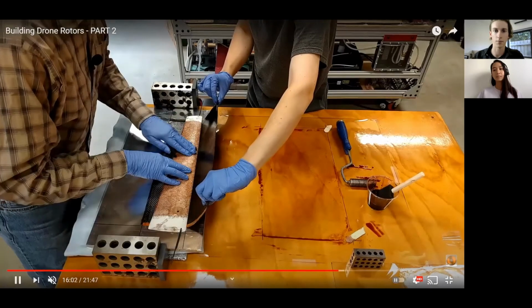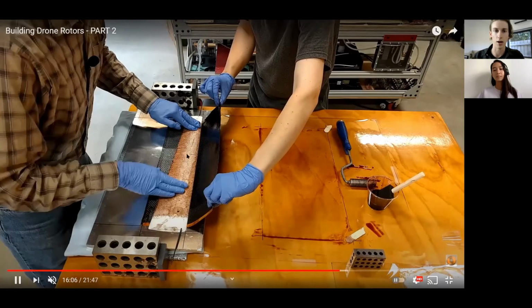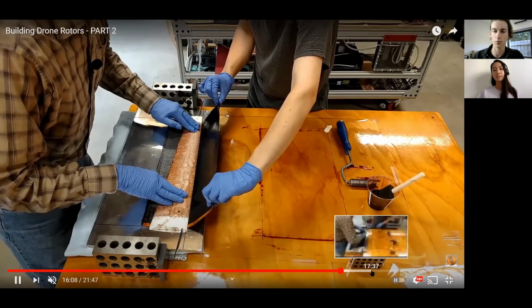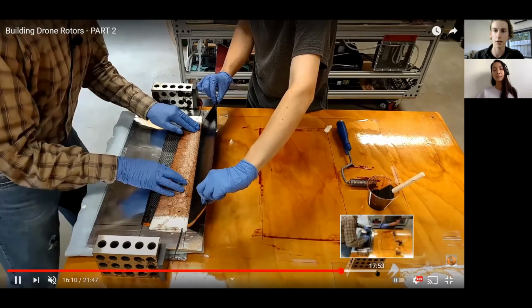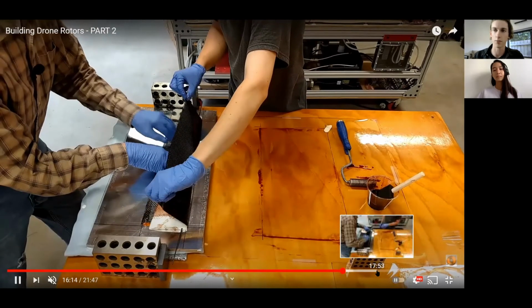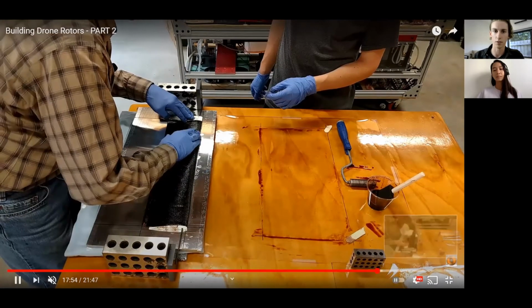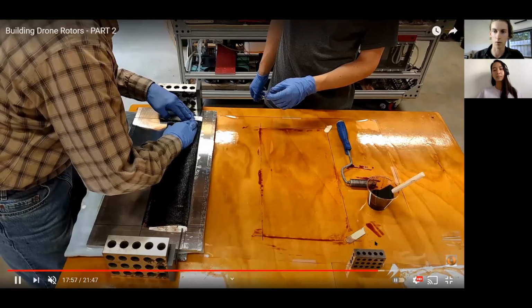And that's going to stick nice and tight to that mold, and it's going to dry the epoxy. You put it up to an elevated temperature. I can't remember exactly how hot it is, might be something like 50 degrees for 5 hours. And that will solidify all the material. You want it nice and tight over that mold.